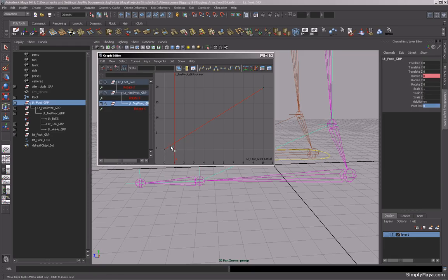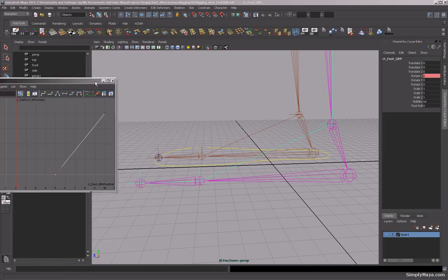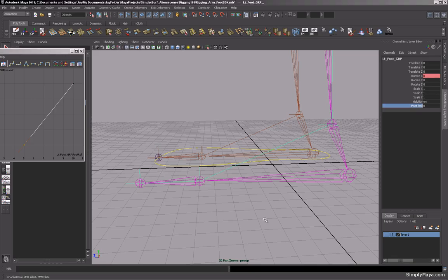So as you can see, the rotation, what it's saying is the curve is starting here. So what we need to do is grab this, and bring it along and down to frame 5. So if you just grab that and just middle mouse, it should snap to each of those frames, like so. So now let's just hide this out of the way. If I go to foot roll, that now comes up and adjusts very nicely indeed. Okay, so that is that foot rotation pretty much complete.